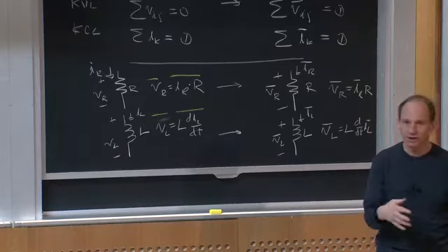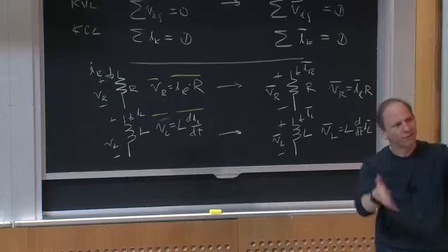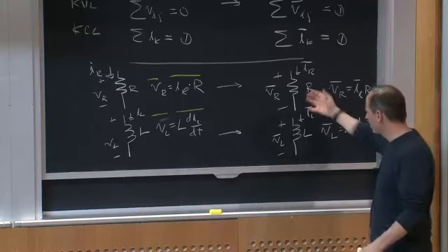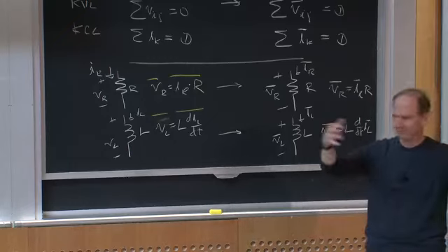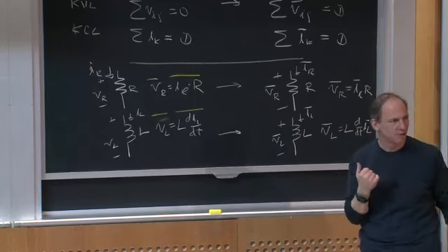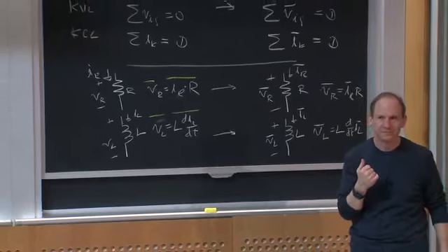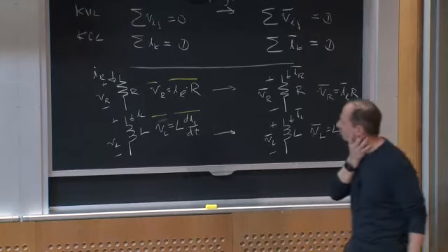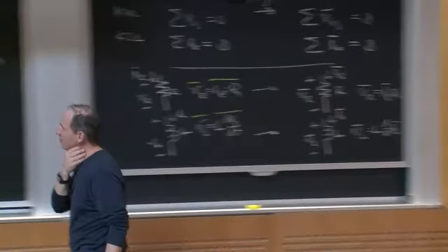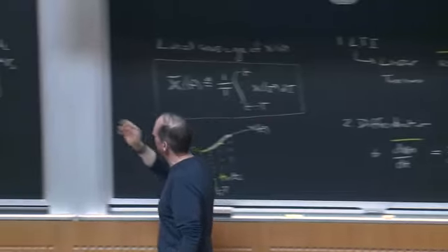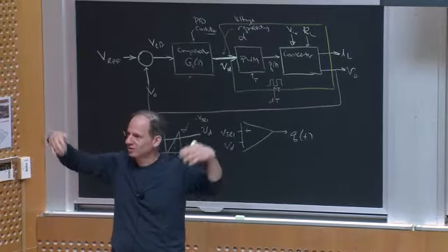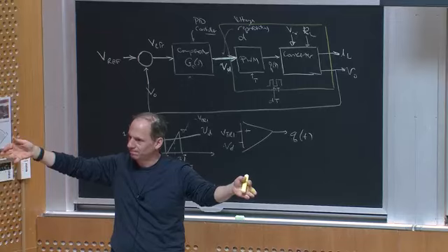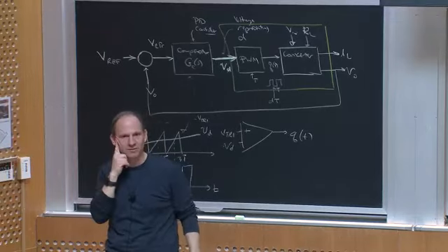So the beautiful thing here is if I go to average my circuit, the resistors, inductors, capacitors, sources just become the local averages of themselves. Okay? Well, that's nice, because what I'm suggesting is I can come to this circuit and take its local average and come up with a new circuit that does the same thing but without switching ripple. Does that make sense to everybody?